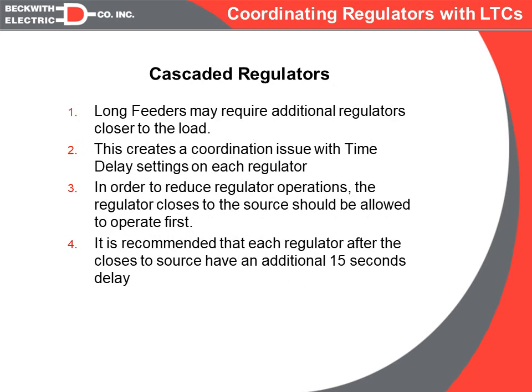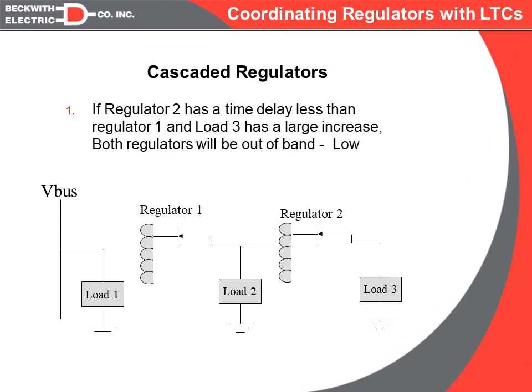Now, if we have a combination of either feeder or bus or LTC regulation inside the fence and regulators outside the fence, we have to coordinate them, and that is done via the use of the time delay. And why we need to coordinate them is shown on this slide. So, if we assume that we have an increase in load down here, that is going to cause a voltage drop across the entire circuit. If we were to allow regulator 2 to raise the voltage first, that would bring this portion of the circuit back into what we consider good voltage, but this portion of the circuit would still be low.